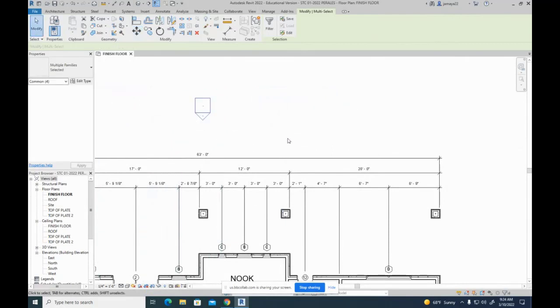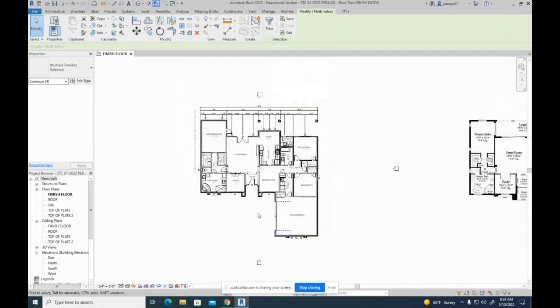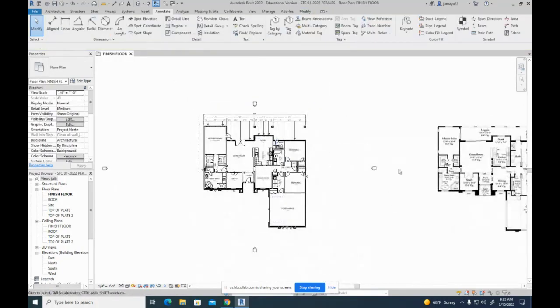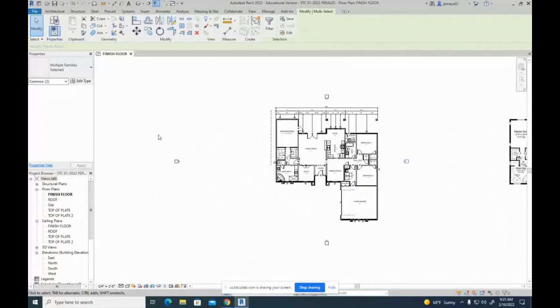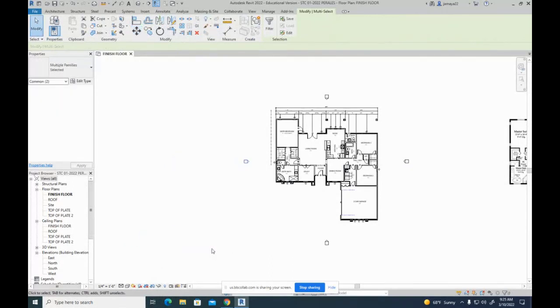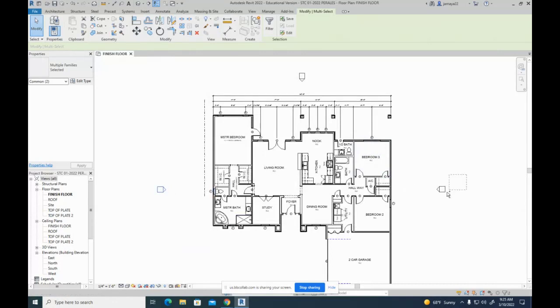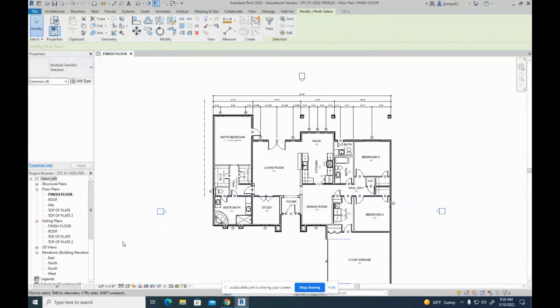Basically what you're trying to do is line it up with the middle of that dimension line, so that it looks nice and organized, right? So this one would be centered, and then hopefully this one down here would be centered with this middle dimension. And then I do the same thing over here. I'll grab this one, move it in as close as I can, then grab this one. I didn't dimension them on purpose, because I want you guys to dimension the other three sides, and that way I can also see where you are in your dimensioning skills, and guide you on what is missing. Then I would do the same thing. That one's still selected. Grab this one, and then move it so that I can center it in the middle of the overall distance.